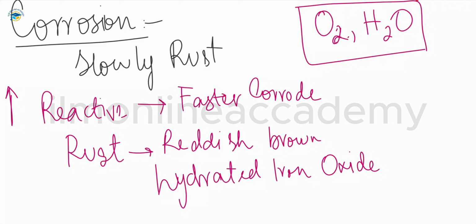Not that rusting only occurs on iron or steel objects, there are many other objects on which rusting can happen. So this is about corrosion and rusting. It is the problem that is present when a metal is attacked by the air, water or other surrounding substances, and it is said to corrode. When iron corrodes, the rust forms flakes and does not form a single layer. The attack on the metal can continue over time, the rusty flakes come off, and holes can be formed in the iron sheets by the rusting process.